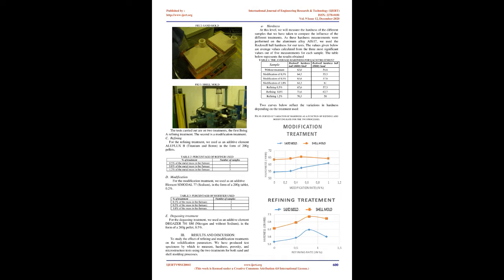During all of our castings, the alloy was heated in the same furnace to a temperature of 650 degrees Celsius without heating any other metal. We cast different specimens allowing us to subsequently perform the various tests, which are a micrographic analysis, the recording of thermal curves, tensile tests, and hardness tests. The objective of the study is a comparison of the manufacturing of a hypereutectic Al-Si17Cu4 sample using two processes.